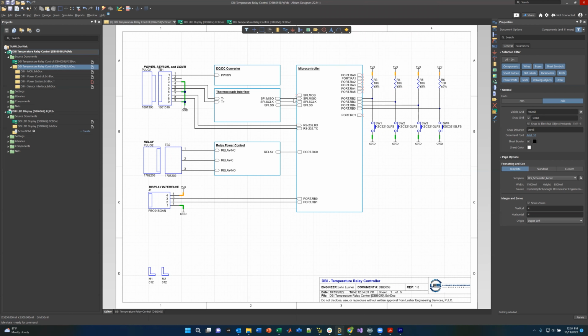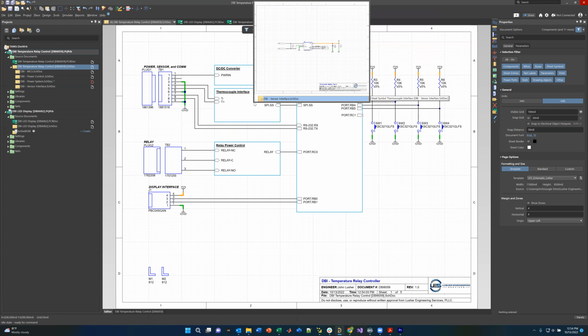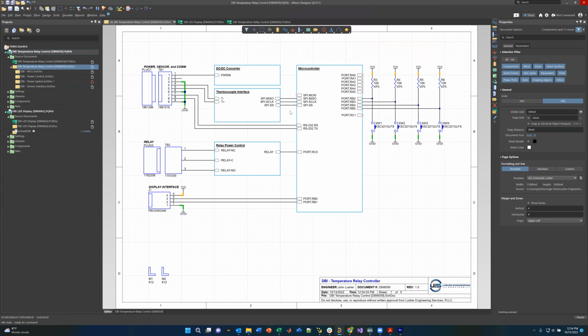In other words, there's a digital out pin where the digital data is going to go from the thermocouple reader into the microcontroller. The microcontroller is going to send clock signals to clock the data out, and there is a slave select or a chip select to actually select and get the data from the chip in question, because you can have multiple readers. In this case, we have one. SPI also has what we call master out slave in. In other words, that's data from the microcontroller to the device in question. In this case, this device does not require that.